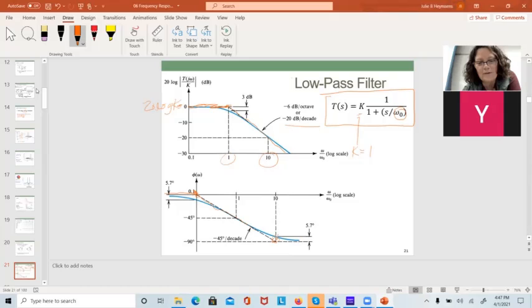Yeah, it's an error. If you have modern processing tools, you can calculate these exactly in something like MATLAB, or in Multisim or Mentor Graphics. But if you're just drawing a sketch by hand, you just ignore that 5.7 degrees, and you ignore that 3 dB. But every engineer kind of has it in their head that I'm going to be 3 dB off. Or if I actually take it out in the lab and measure it, where it hits that 3 dB point, that is where the omega naught is. 3 dB less than whatever K is.